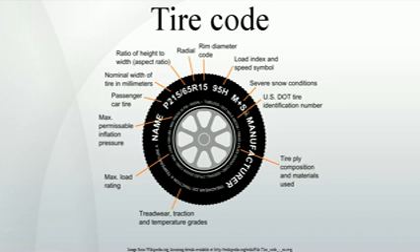P indicates that the tire is engineered to TRA standards, and absence of a letter indicates that the tire is engineered to ETRTO standards. In practice, the standards of the two organizations have evolved together and are fairly interchangeable, but not fully, since the load index will be different for the same size tire.